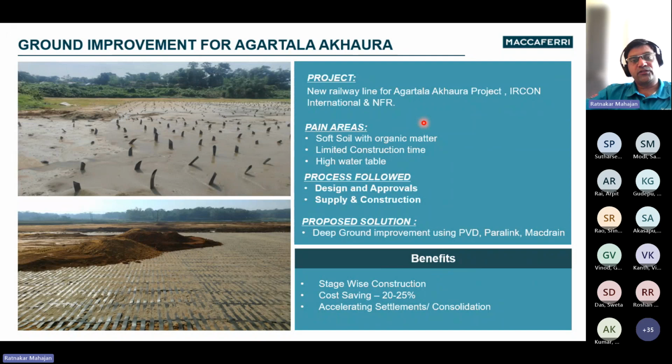So because of the very poor soil condition, it was designed to accelerate the settlements which may occur over a period of time. And the acceleration of settlements was done using the prefabricated vertical drain. A layer of high strength geogrid was placed on top of this prefabricated vertical drain. The purpose of this high strength geogrid was, when we construct the embankment, we can reduce the number of stages and avoid the slip failure.